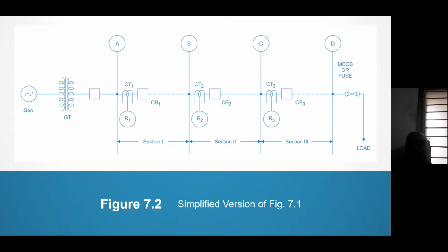This is wrong. If R3 operates, the fault is disconnected, fault current is 0. Now normal current is flowing, so there is no question of R2 operating. I do this joke so often with students to make them understand that they should understand protection fully, not with half-heartedness.